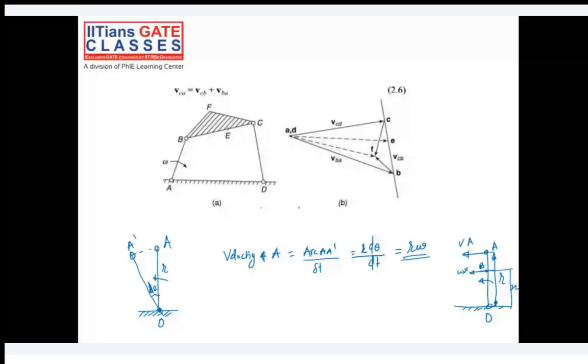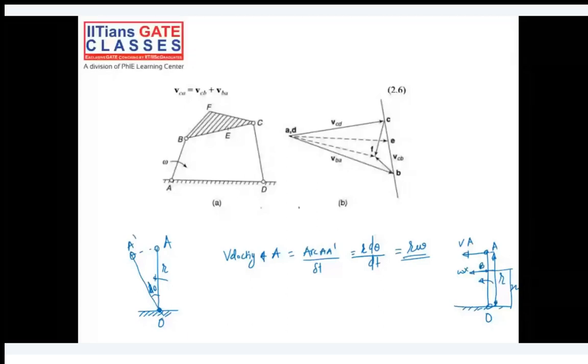We got a question from Shruti here. Can we say the velocity of point B is less than at A? Yes, for this particular example we can say that, because X is smaller than R and omega is the same for both points. So the linear velocity at point B will be less than that of A.